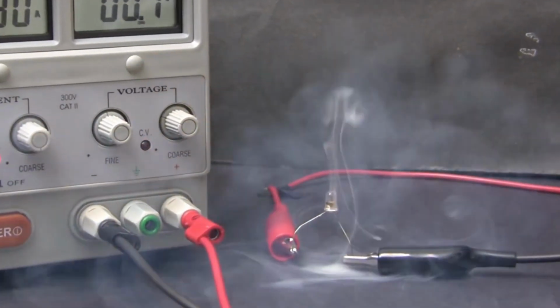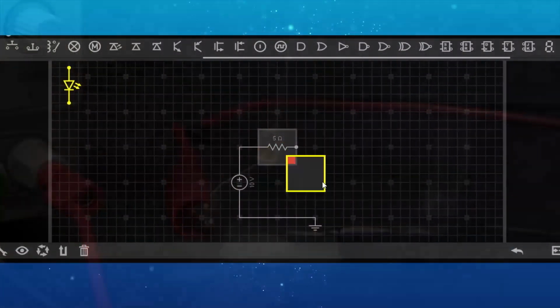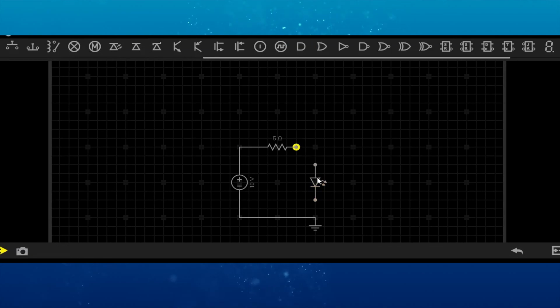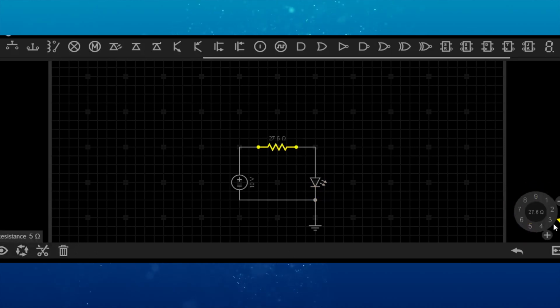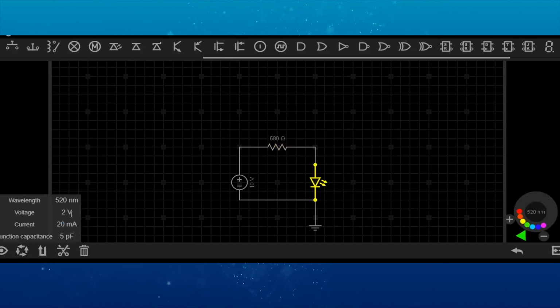You are probably wondering how to not burn the poor LED as we saw at the beginning of the video. We will add a LED to our DC circuit, and we now have to dimension the resistance correctly in order to limit the current flow to an appropriate value. For the white LED, the typical current limit is 10 mA, and the typical voltage drop is 3.2 volts. Once we have 3.2 volts dropping in the LED, the remaining 6.8 volts will drop in the current limiting resistance.